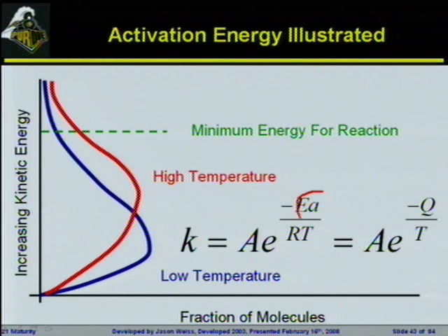We will talk about the activation energy of the cement paste reaction down here. Obviously all of us know the gas constant, all of us know the temperature. But we will also see other terms get introduced. Since the gas constant is simply a constant, you will frequently hear people in the cement industry refer to this Q factor, which is simply the activation energy over the gas constant.